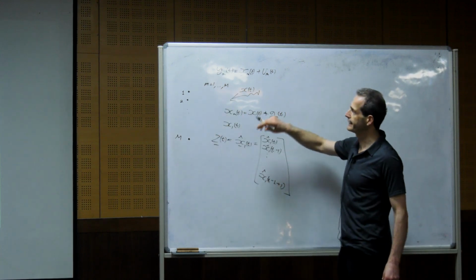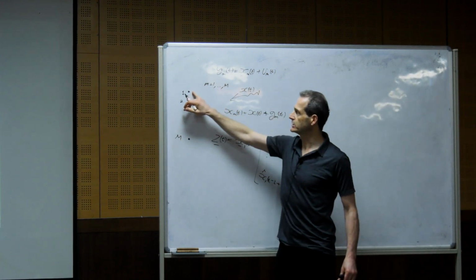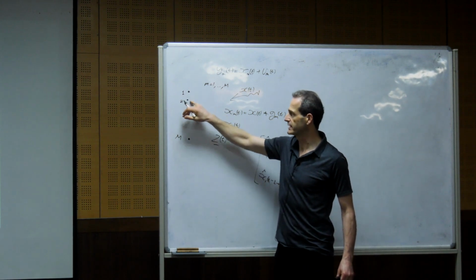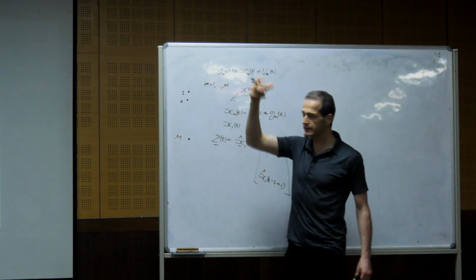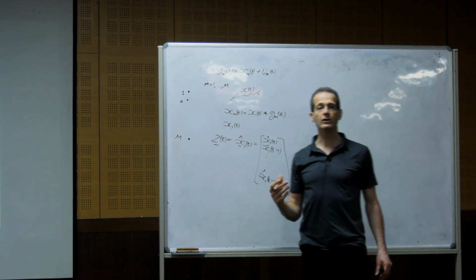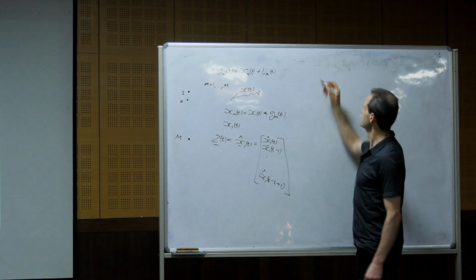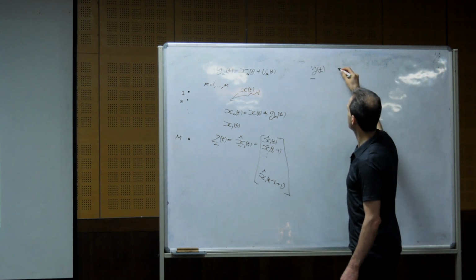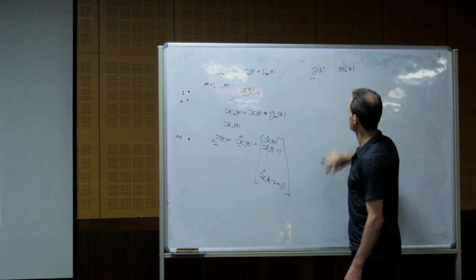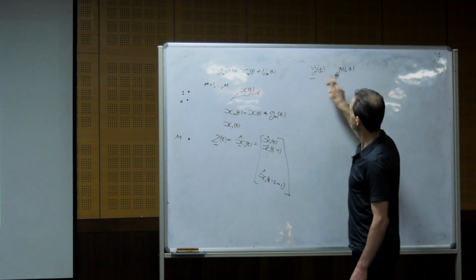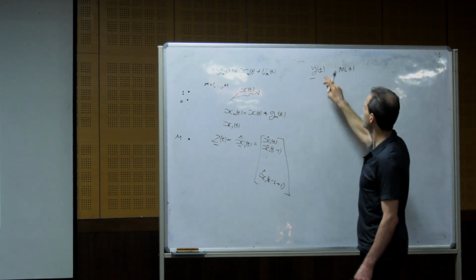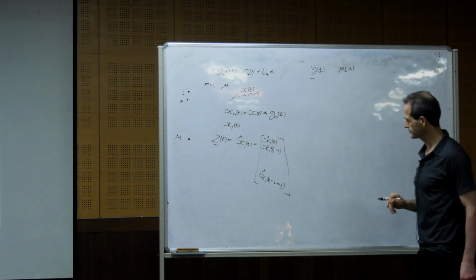So we take L samples from each sensor, and we concatenate them into a long vector of length ML. So we have a vector y(t) of length ML by 1. It contains L samples from each sensor concatenated over all the sensors.